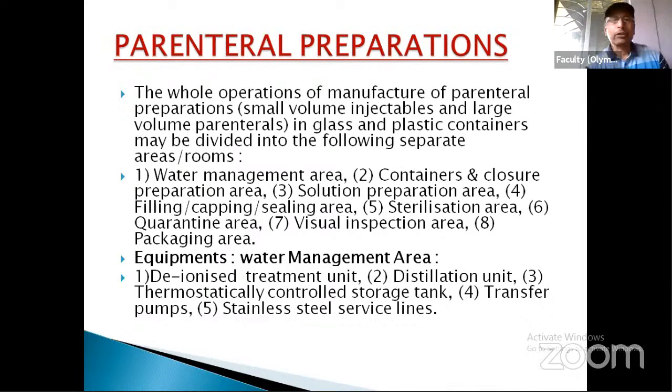So one section is the water management area, another is the containers and closure preparation area, where you have to prepare your containers and closures. Your solution preparation room, where you will prepare the actual injectable. The filling, capping, sealing area. Sterilization area. After that, you have to sterilize it. Some preparations are finally sterilized, and some preparations are sterilized during manufacturing. Anyway, you have to provide a sterilization area.